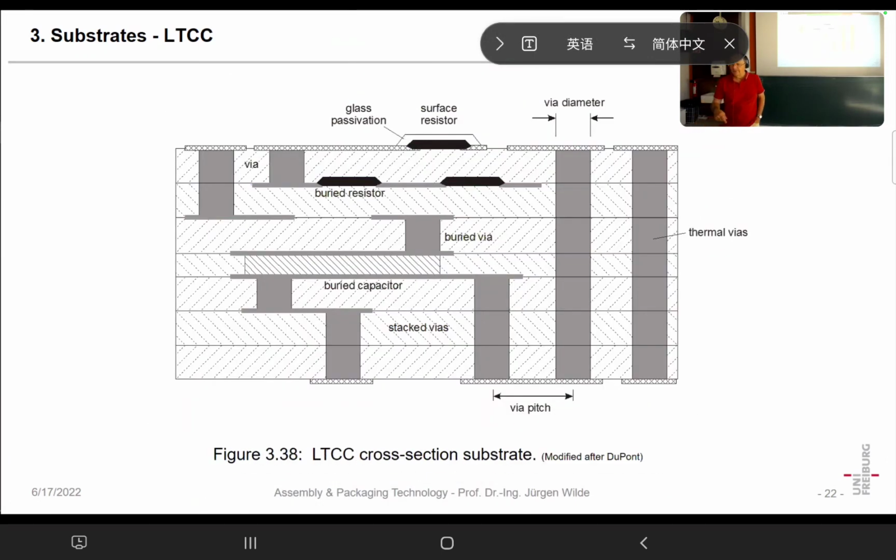here. That's a thermal vias going through, and so that simple example shows us only 1% of silver more than doubles the thermal conductivity. So having only a little silver here going through with full through vias, then we can dissipate much more heat, and we can easily be as good as alumina material.